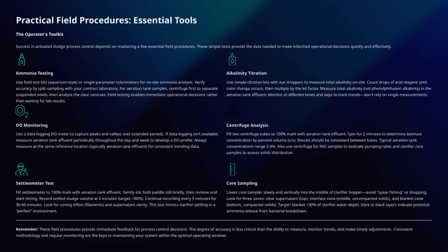It's best to monitor at different times and on different days to identify trends. Single measurements won't give you the full picture. Moving on to dissolved oxygen monitoring. Using a data logging meter is ideal because it captures peaks and valleys over extended periods.